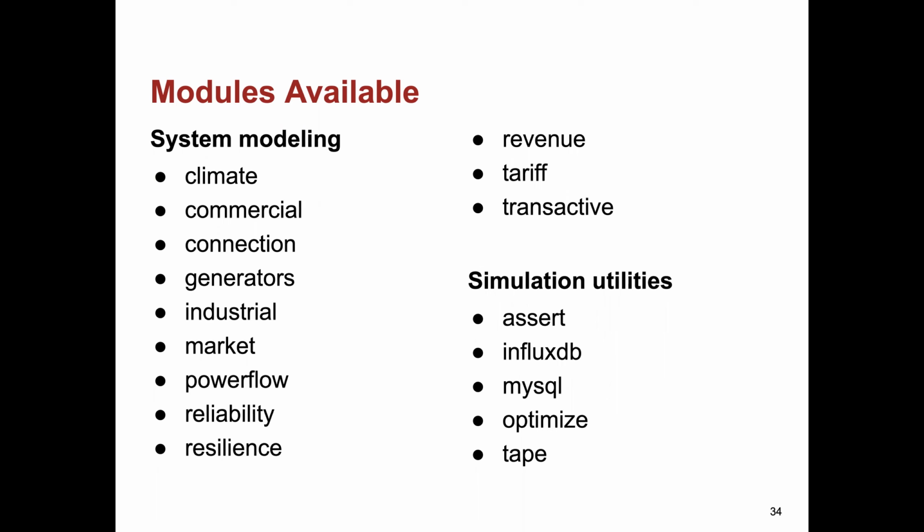There's a commercial buildings module that implements essentially all buildings that require three-phase service. A connection module allows you to connect to external things like hardware devices. This is particularly useful if you're doing hardware in the loop simulation, and you need to get GridLAB-D to communicate directly with those devices, especially in an outbound direction, but it supports both directions.